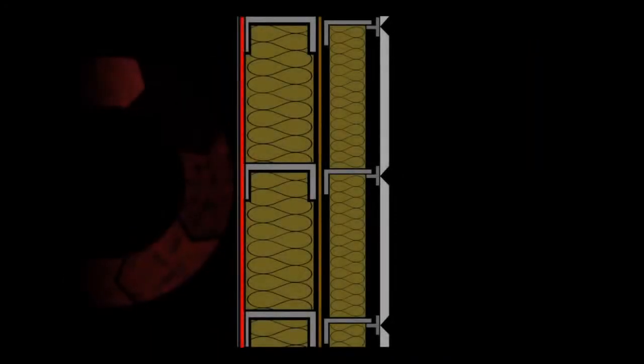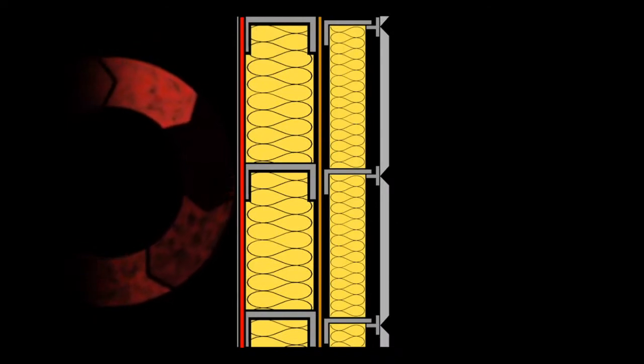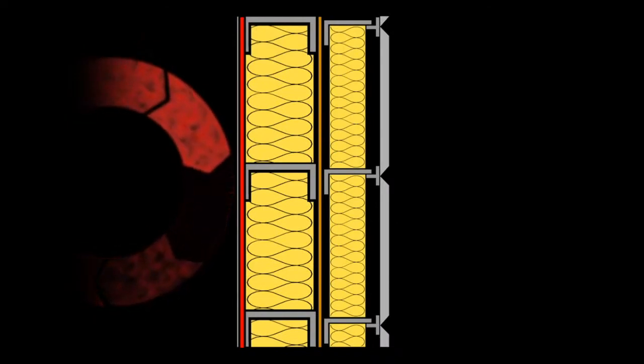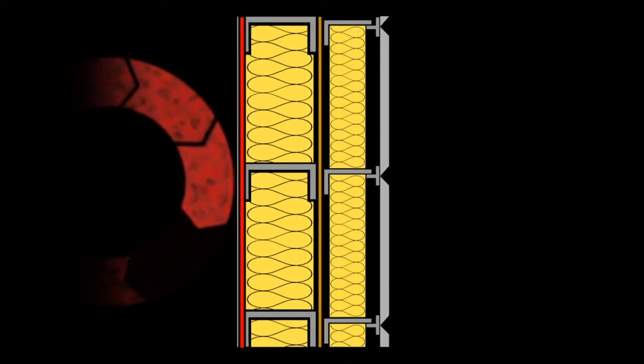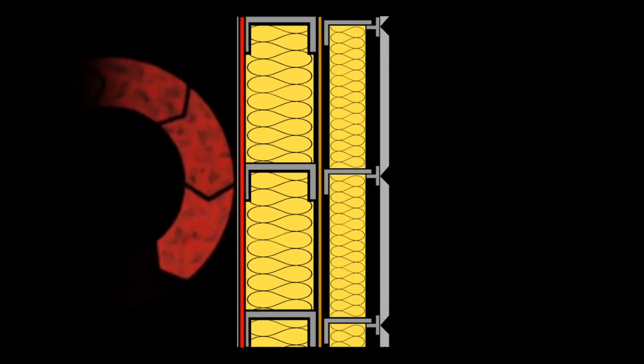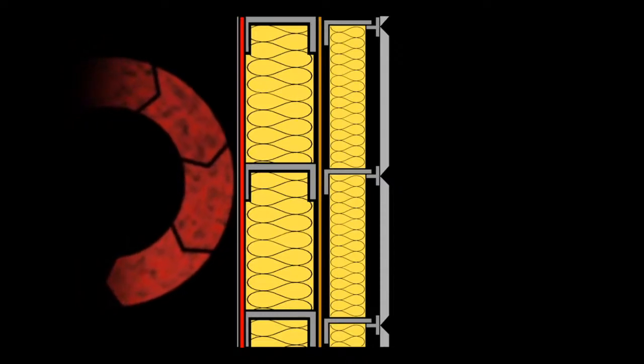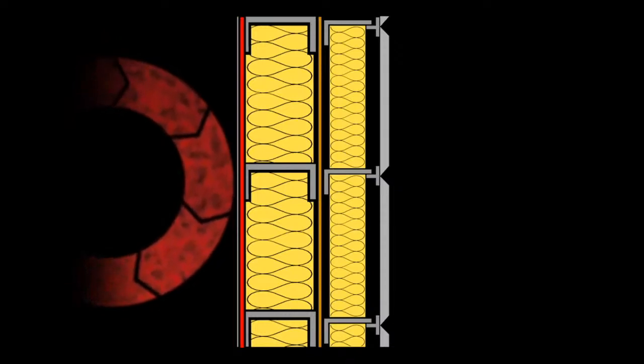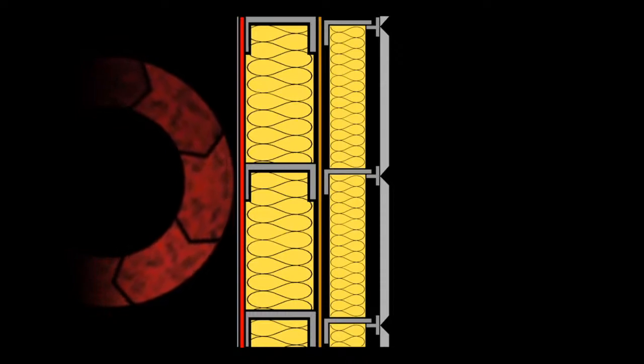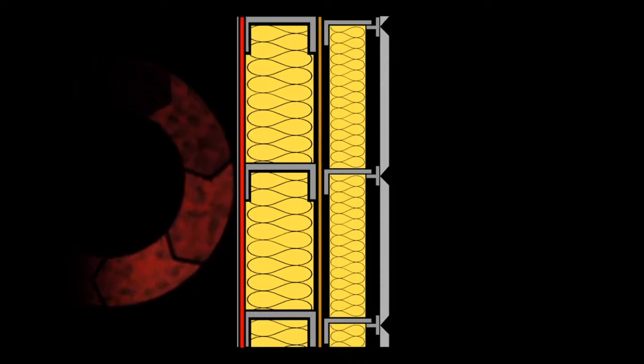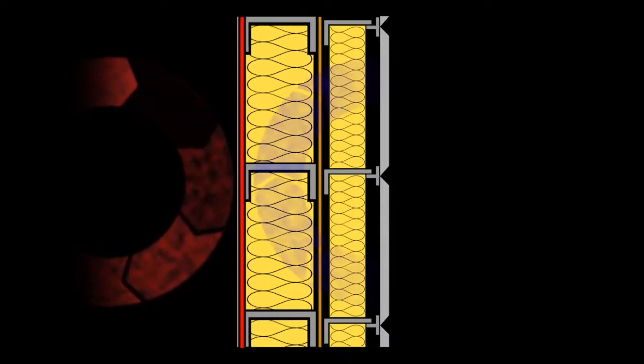Traditionally, air barrier membranes have been installed internally on the warm side of the insulation. Typically, these also function as vapour control layers. This positioning requires the air barrier to be sealed at all surface and structural penetrations and remain sealed. If the membrane is damaged either during installation or following trades at later refurbishments, for example, then both air leakage and moisture vapour ingress problems can arise.